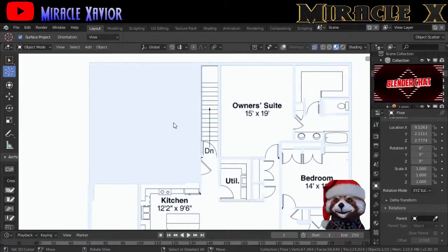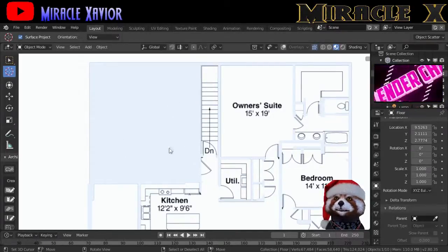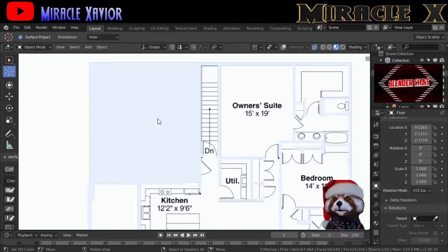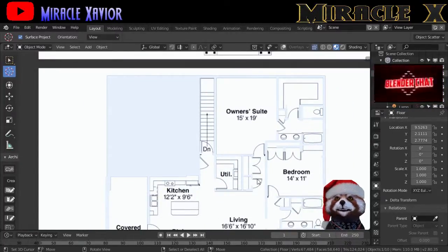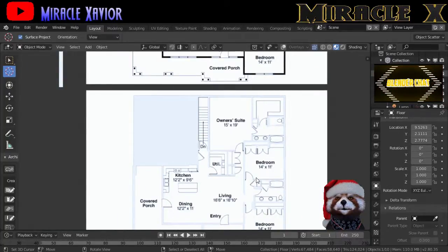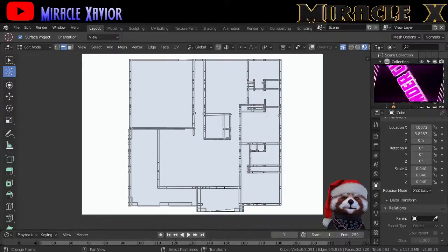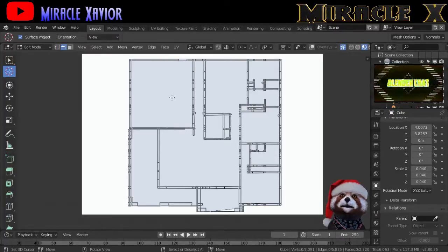But if you just follow the way I showed you previously, all you have to do is just snap around, just make this filler. That's what the F is for, it just fills the area of your geometry. And you do the same thing with the whole room until you get it to look like this. Alright, and then once you fill each room, it looks like this.